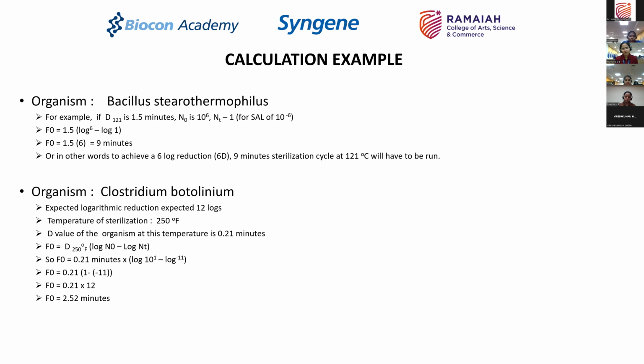For a given load, you establish an F0 based on Bacillus thuringiensis, and that has to be repeatedly achieved every time. If you cannot achieve that, if your Bacillus thuringiensis biological indicator, which you kept with every autoclave cycle, was a different data point, then there is a problem in the autoclave which you need to address. Maybe the steam flow was not proper, or maybe the air evacuation was not proper. So this is an important factor which gives you the performance of an autoclave.